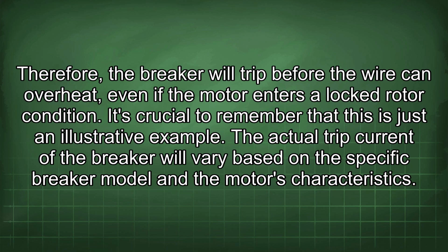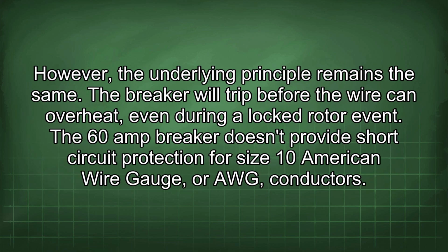It's crucial to remember that this is just an illustrative example. The actual trip current of the breaker will vary based on the specific breaker model and the motor's characteristics. However, the underlying principle remains the same. The breaker will trip before the wire can overheat, even during a locked rotor event.